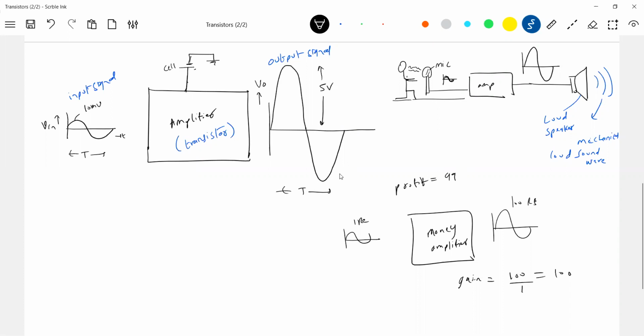Similarly, here we'll define voltage gain. How much did I gain? Voltage gain should be output voltage by input voltage. The symbol we use for voltage gain is AV, a capital A. This is Vout by Vin, or delta V naught by delta V in. So what is the gain? 5 volt by 10 millivolt, which is 500. That is the gain.